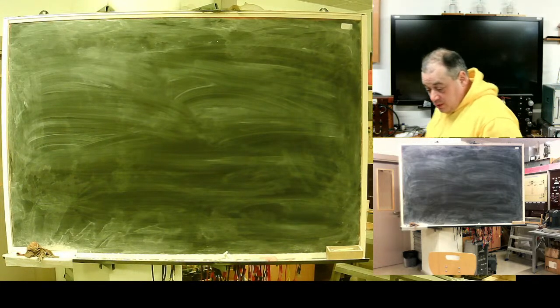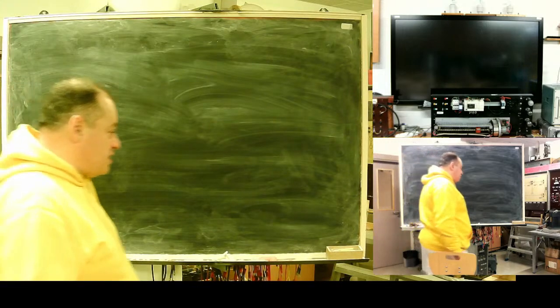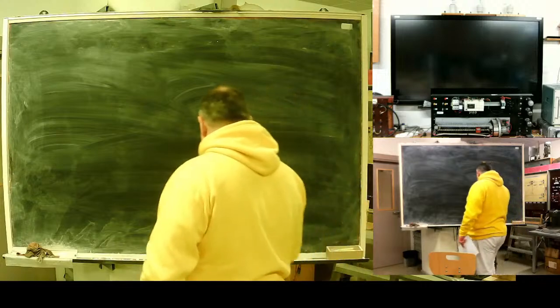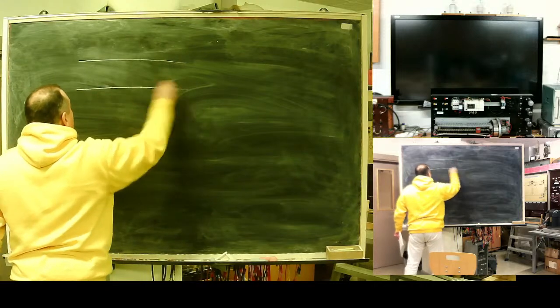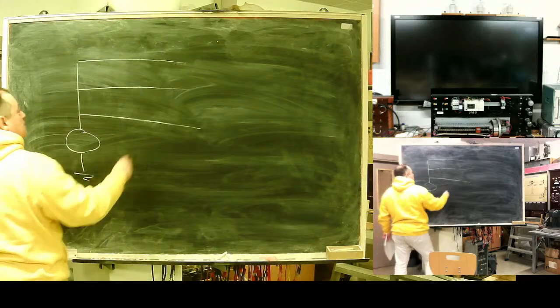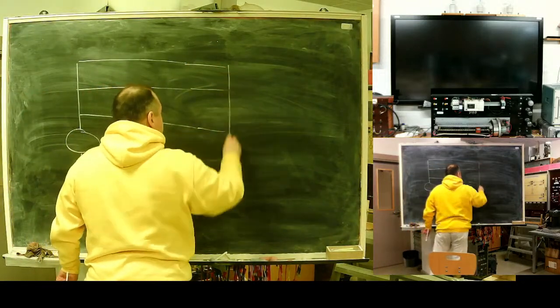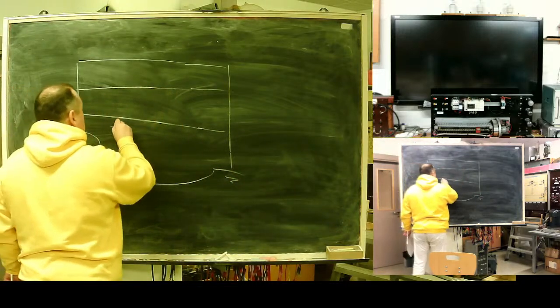Carson's model is two magnetically coupled wires over the conductive ground. But we don't have two wires, we have three wires, and we need a model for zero sequence. Again, wire, wire, wire, some source, ground, current returns.